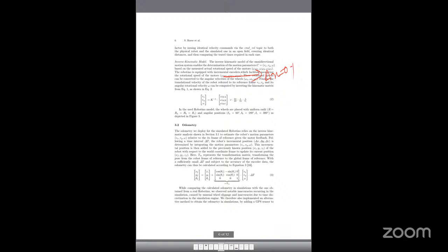Time. Okay, so 0.1 second time the robot traveled. 0.1 second. I will write 0.1 second. So delta x will be 5 centimeter, delta y is equal to 0. So previous position was say 2.5 and 1.8. So the new position will be old position plus increment, that will give you the new position, right? So 2.5 plus 0.05 will be 2.55.